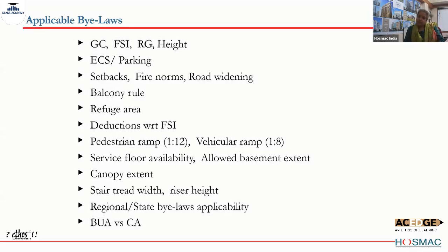No, 24 meters. 24 meters we give, we allot a large refuge area, 4% of the built-up area which is above this refuge area. 4% of that built-up area is the refuge area which is given at 24 meters if the building is tall. So this comes into play for taller buildings and is unrefutable. You have to give refuge areas.